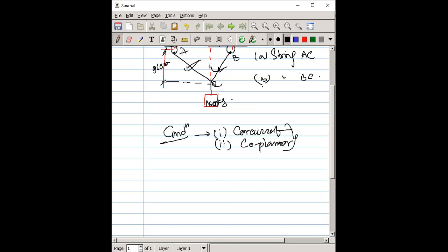So what is the free body diagram? Free body diagram is when you just put all the forces with respect to any point or any line, that is called the free body diagram, where all the forces are included, which is similar to the system forces. So here if we draw the free body diagram, how to draw? See, this is your point C, and from point C all the forces pass, means concurrent forces are at point C, concurrent point if we say. Then this should be your mass.